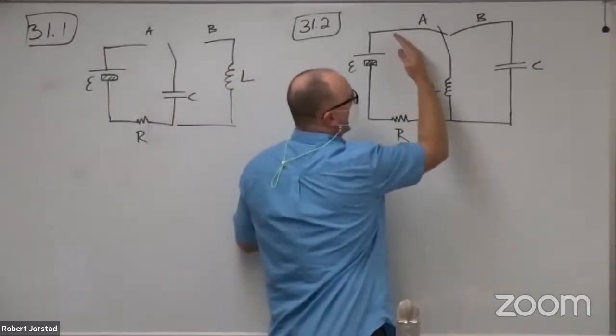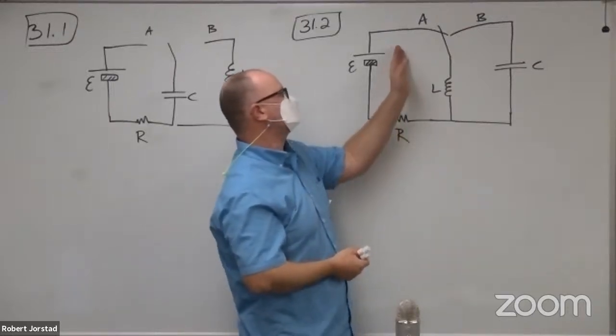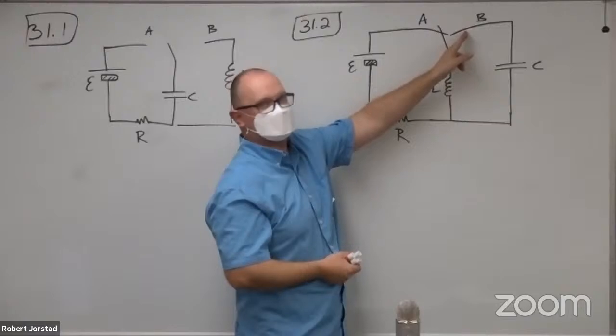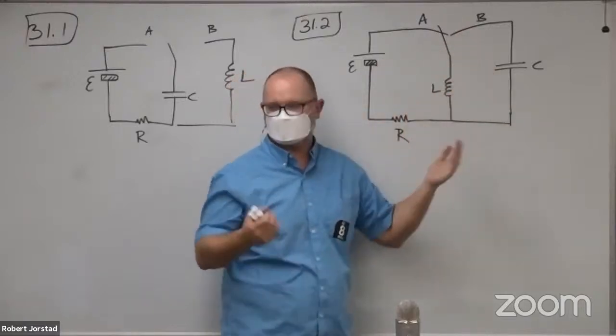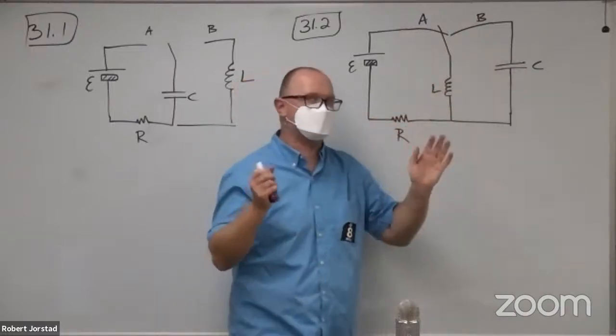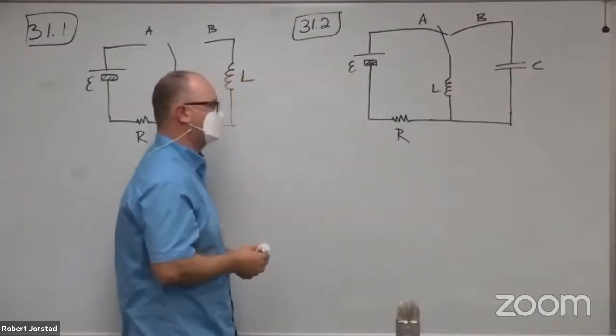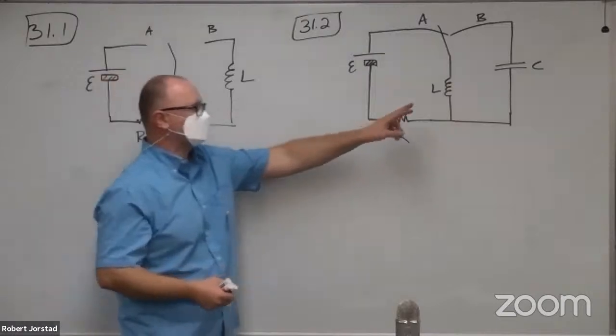Cool? Now, in practice, what does this mean? As long as you switch it very quickly, it's not a big deal. And so the issue is, if you're switching this over here and you take a long time, the capacitor could charge up off the battery instead of off the inductor, and that might screw things up. So we're going to assume that you can do this so quickly and it's a perfect ideal switch, and it doesn't really work this way, but yeah. Now, other than that, we got the inductor stores magnetic energy.